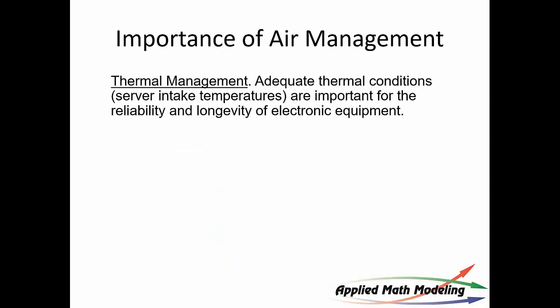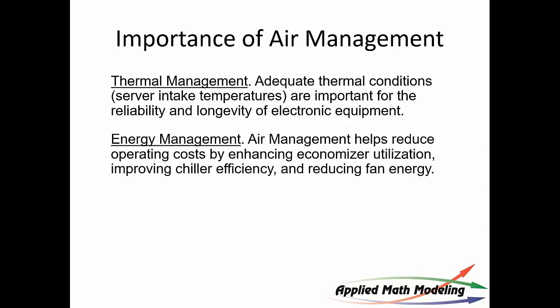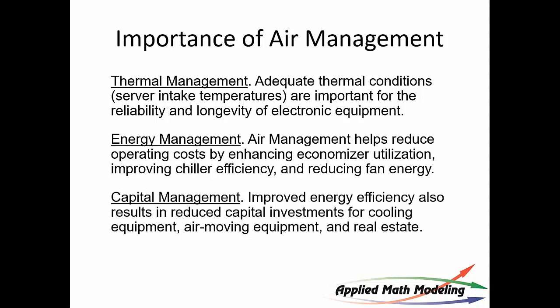So air management is providing the right amount of air for the servers, and that relates to energy because delivering cold air is expensive, and then that relates to capital because if you don't set it up correctly, you will shorten the life cycle of the cooling equipment. So it reduces capital investments for replacement. You can get more life out of them. So air management is key for data centers. It is how we cool them today.